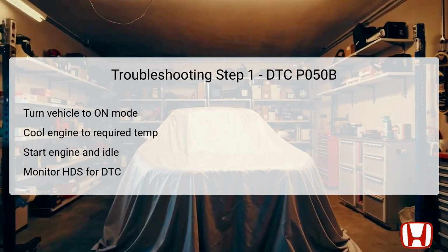Once the engine is sufficiently cool, start the engine and allow it to idle for at least 10 seconds. During this period, use the Honda Diagnostic System HDS to monitor the onboard diagnostics OBD status specifically for code P050B. This initial step lays the groundwork for further investigations.